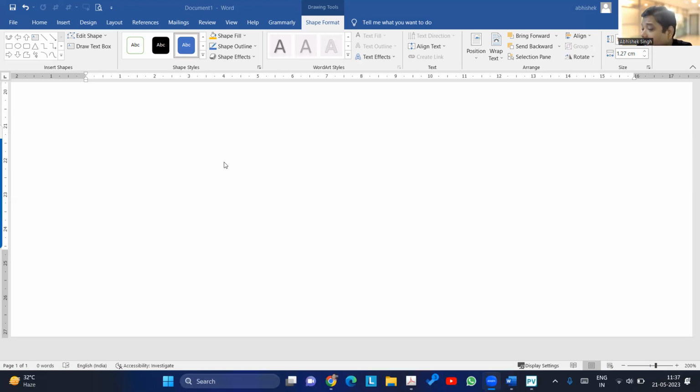it's really not a good practice to use that. I hope you guys are doing impact testing. See, even the code does not matter here. This is a matter of safety. So even the code will not say anything about that. You have to do impact testing for the material to remain safe.